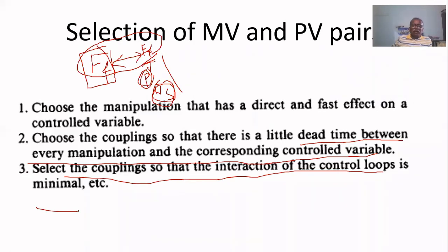As we have already seen, all four variables can be used to control all four process variables. That's why each has some effect on the other variables. So if you adjust one, the other three also will change. That is called a disturbance because of changes in one particular process variable. That is called interaction. For example, I want to adjust temperature. If for small changes in WS there is a large change in pressure, then I cannot control temperature by WS.